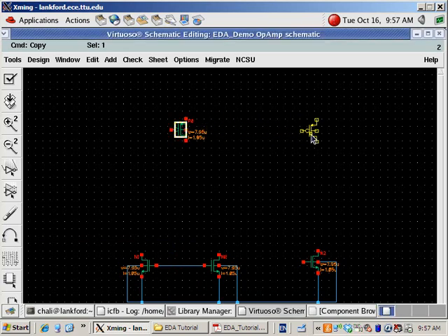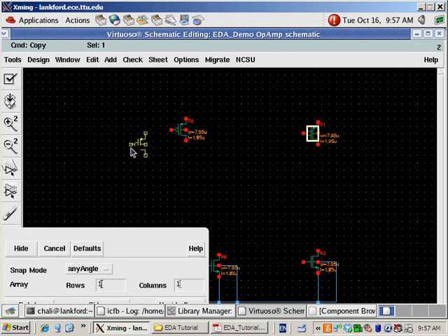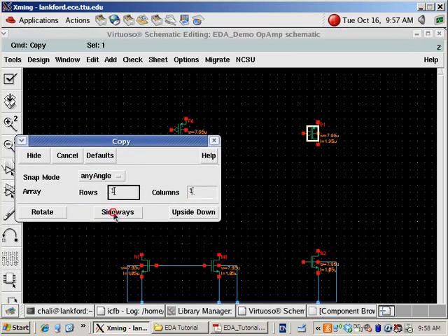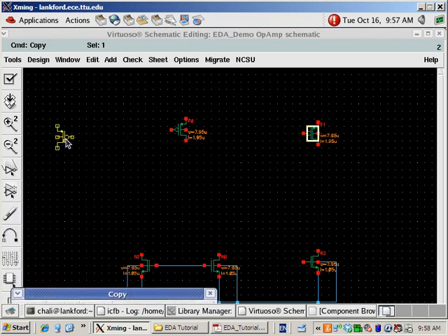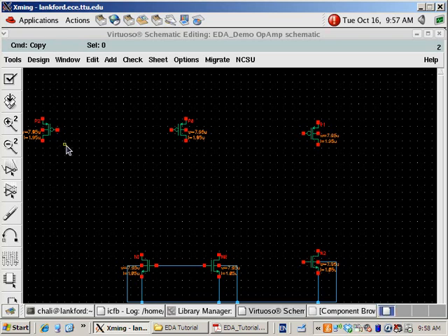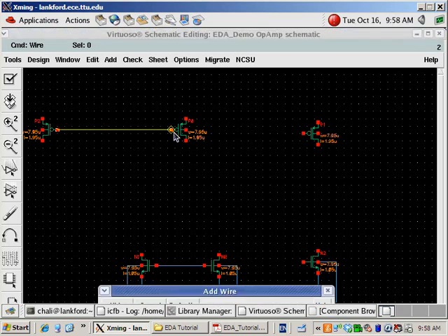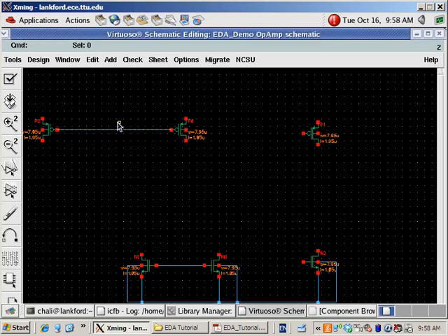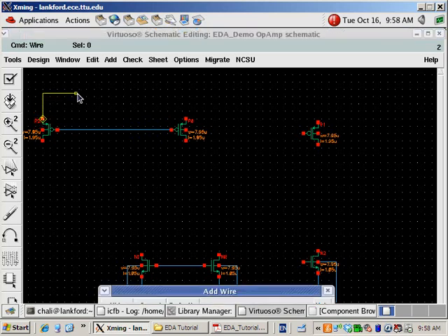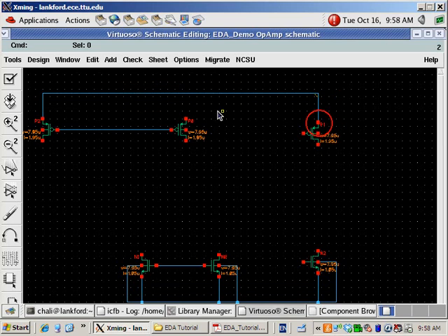Imagine that if you fabricate a bigger transistor, then you can make it more accurate. The error will be relatively smaller, right? The top 3 PMOS transistors are nothing but a current mirror. So we want good matching, and we want to minimize the process variation, and that is why for the top PMOS, the length is larger.